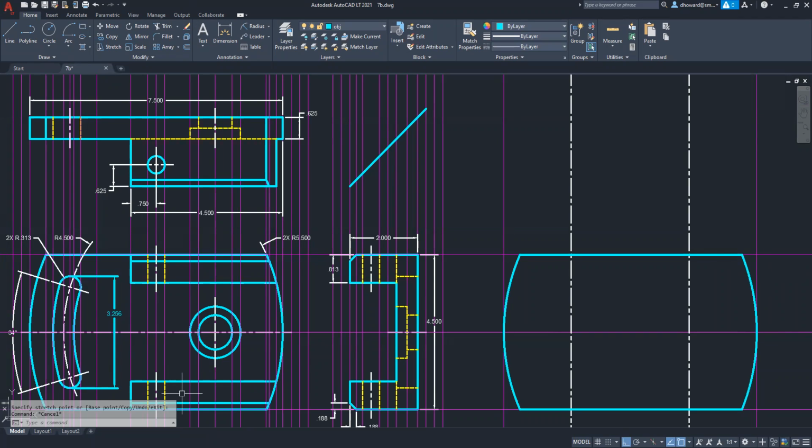I had to do that to create the arc because that's the only thing I had. But the truth is that's a really bizarre way of dimensioning it. A much easier way to dimension it and build it is giving us the arc length between its centers, which is 34 degrees, or half of that would be 17 degrees from center. So that's a good way to do it.